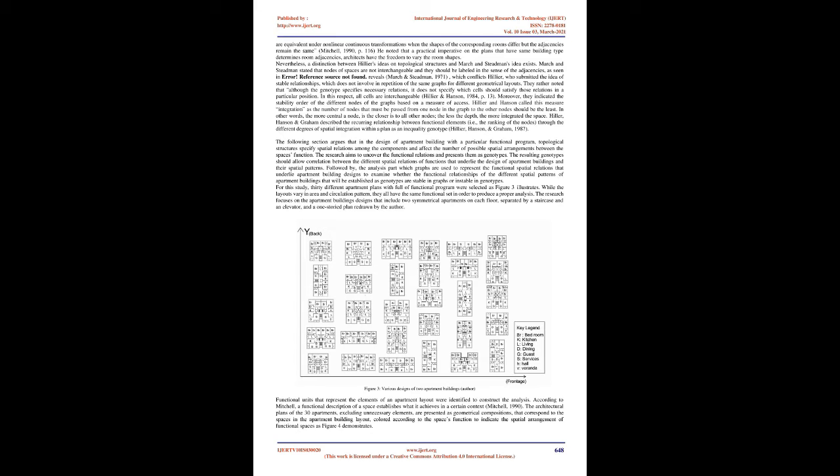(Ghanem, 1993). Apartment buildings generally include a minimum of 8 living units, with 1 staircase and 1 elevator for the vertical circulation to link between floors. As to horizontal circulation, which the code defines as space for moving from one space to another, its width should not exceed 40% of its length. Figure 1 presents the required dimensions for halls, staircases, and elevators in designing apartment buildings in Amman, derived from Ghanem's book.